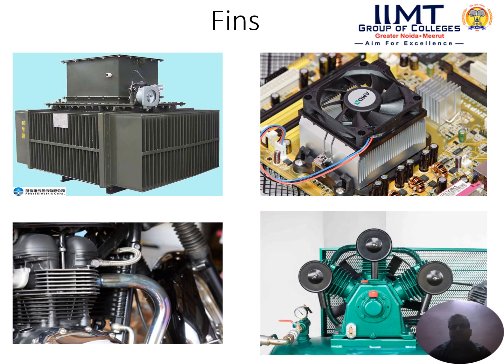If we talk about a small capacity reciprocating compressor, during the compression stroke there will be a continuous generation of heat, due to which there will be a continuous accumulation of heat inside the compressor cylinder. Due to this, the temperature of the compressor cylinder may increase above its working temperature. In all these four examples, we see that when the system has to work perfectly, the system has to transfer heat from the system to the surrounding continuously, and this basically happens by the fin.